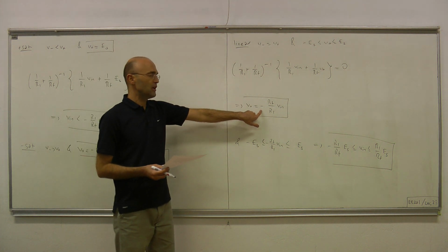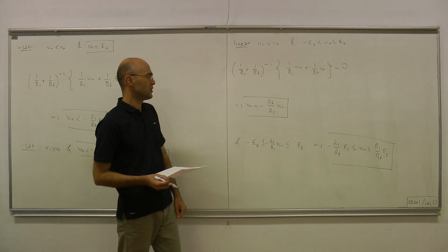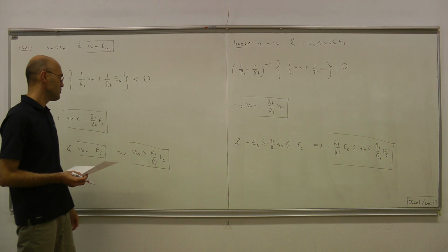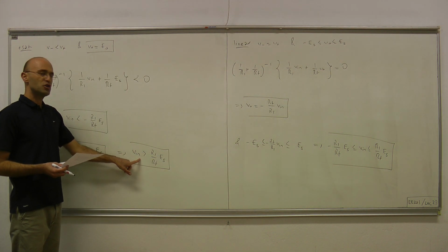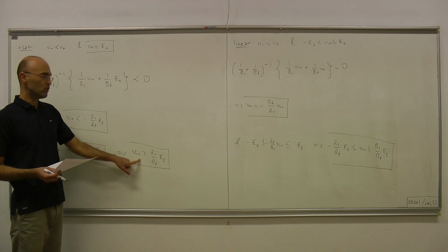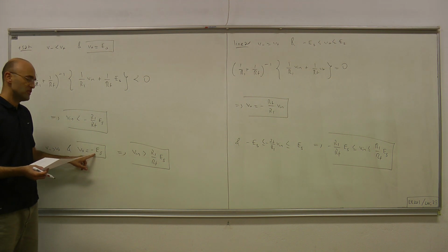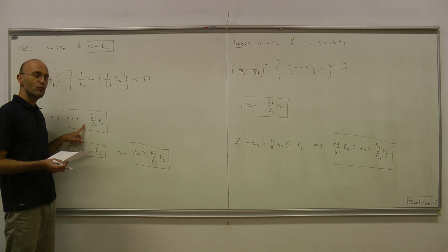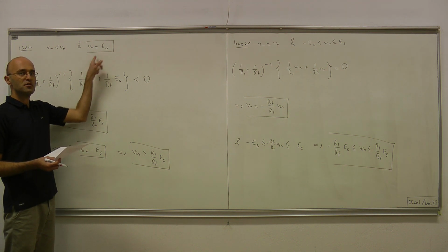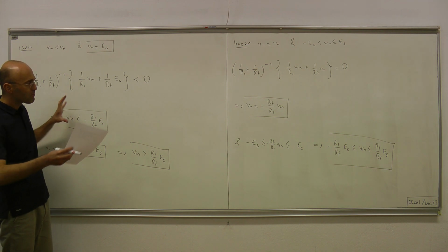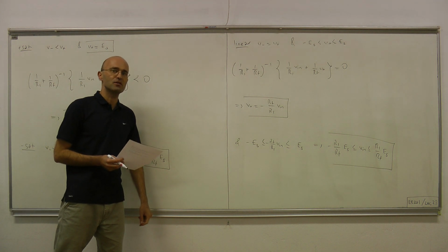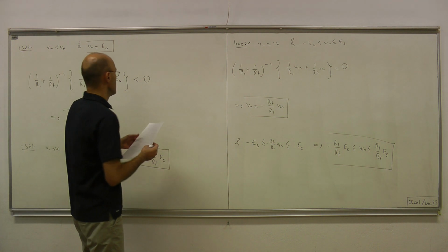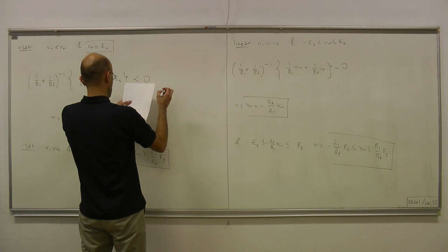This is the input-output relation for the linear region under the condition that the input voltage is in that range. This is the condition on the input voltage so that the op-amp is in the negative saturation region. And finally, this is the condition on the input voltage so that the op-amp is in the positive saturation region. Let's combine those three pieces of information into a single visual whole. And if you do that, this is what we obtain.